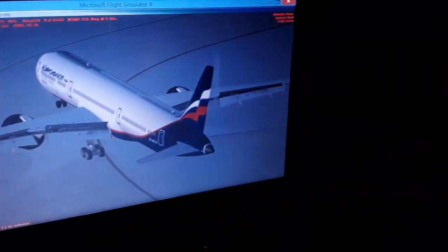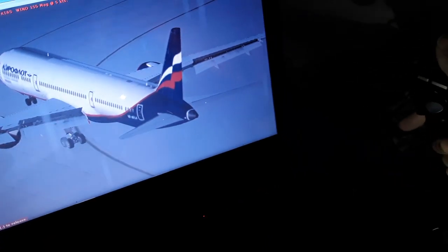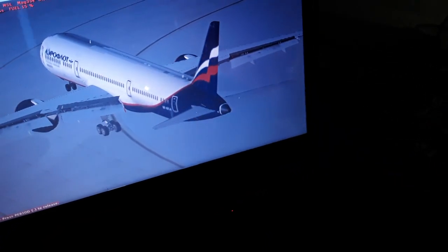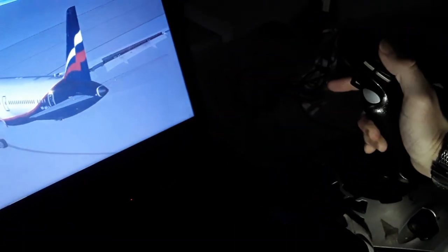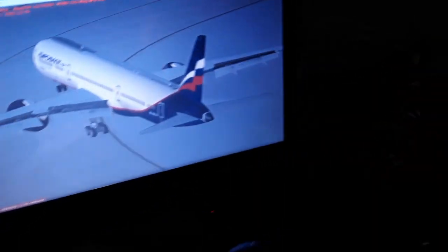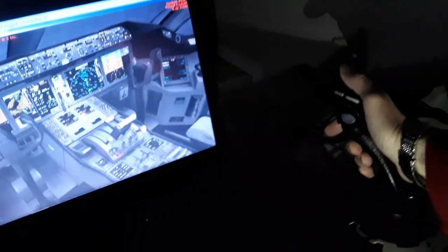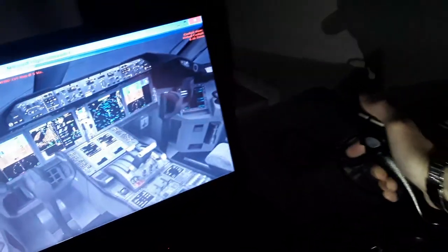We have one more axis over here from wingtip to wingtip. It's the pitch axis. We can climb and we can descend the aircraft like this. As you can see, climb and descend. I use the elevator, the side stick in the Airbus aircraft. Also, we use the yoke in the Boeing 787, as you can see, for climb and for descent of the aircraft.